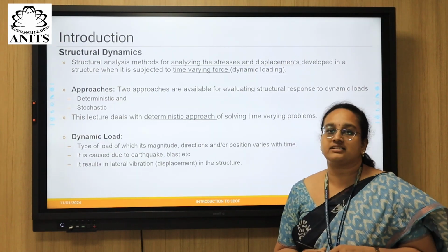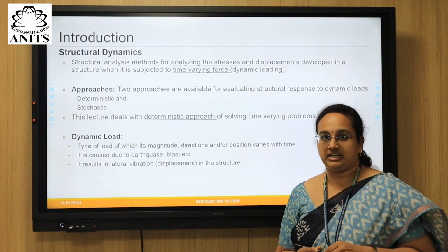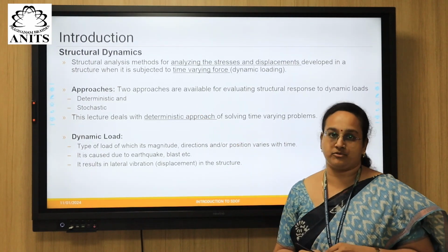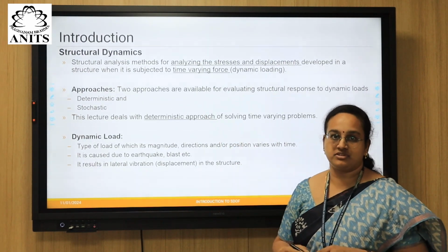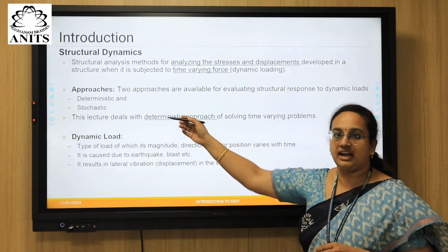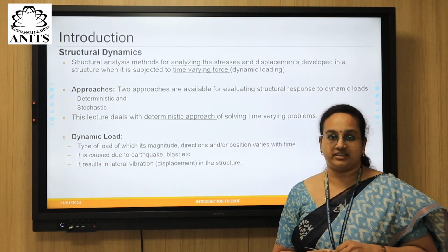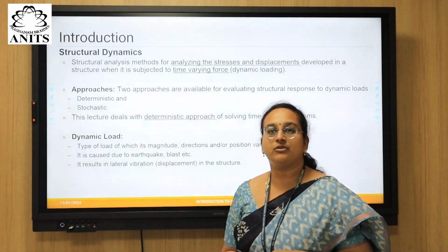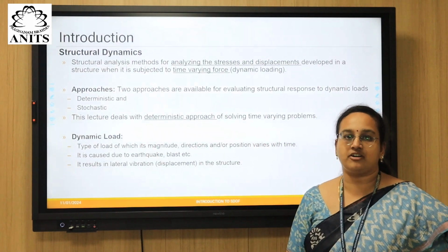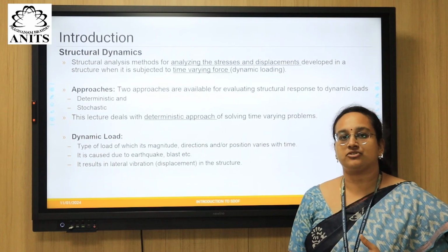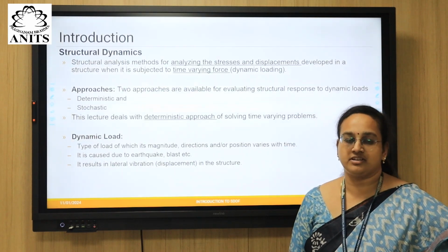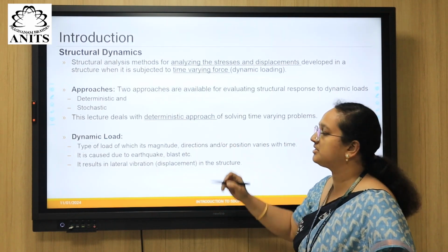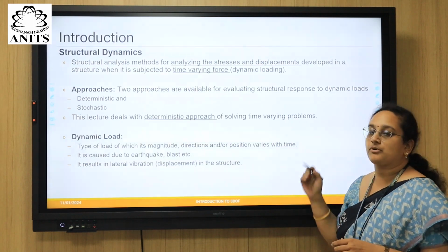The time varying force means dynamic loads. Okay, so this is an extension of structural analysis what we have dealt in previously. So in this structural dynamics, we have different types of approaches. There are two major types of approaches which are deterministic and stochastic. If we say deterministic, we can understand that the closed form solutions are available. Whereas stochastic includes the probabilistic methods of estimation of loads, or it can be estimation of displacements. So it can be anything. So in this lecture, we will deal only with the deterministic approach of solving time varying problems.